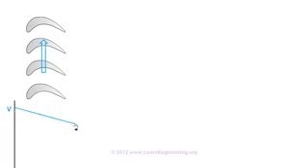Now we will see exactly how a steam turbine is absorbing energy from steam. This is the rotor cross-section of a blade, at a particular length. As the steam passes over, the blade will rotate in this direction. And this will result in energy loss to the fluid. For a typical steam turbine, both kinetic energy and enthalpy come down. So if you plot the velocity of steam from inlet to outlet, it will be like this. As kinetic energy decreases, velocity decreases. Similarly, enthalpy also decreases, like this.